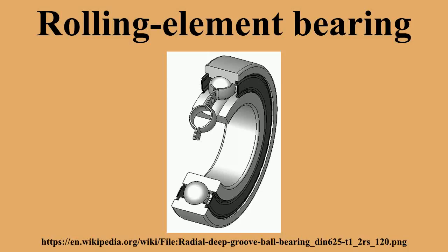Carb bearings are toroidal roller bearings and similar to spherical roller bearings, but can accommodate both angular misalignment and also axial displacement. Compared to a spherical roller bearing, the radius of curvature is longer than a spherical radius would be, making them an intermediate form between spherical and cylindrical rollers. The limitation is that, like a cylindrical roller, they do not locate axially. Carb bearings are typically used in pairs with a locating bearing, such as a spherical roller bearing.